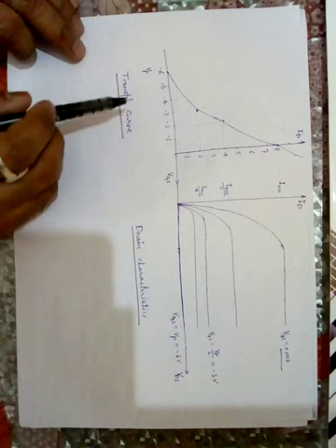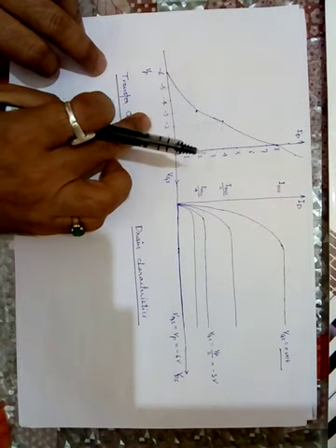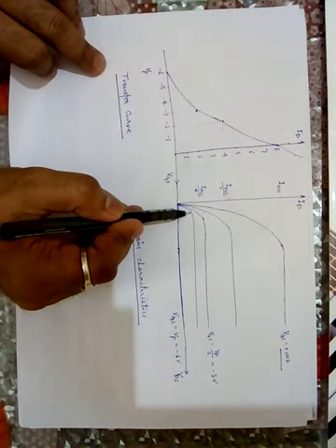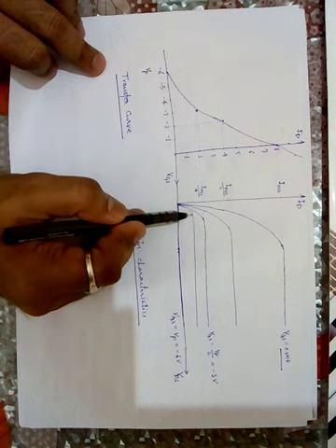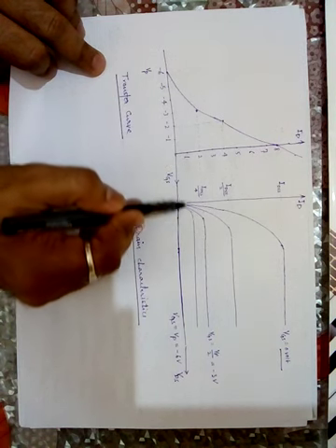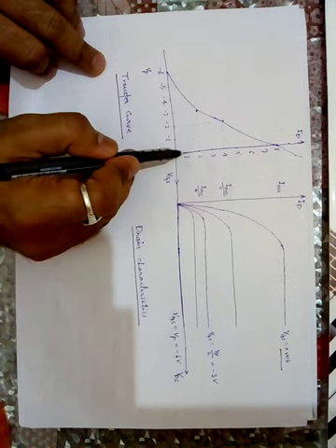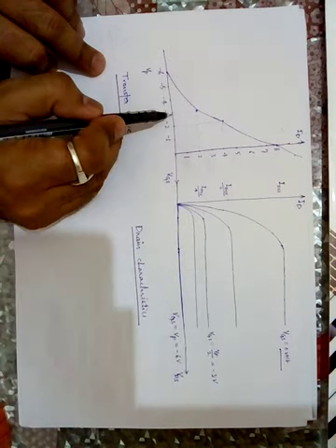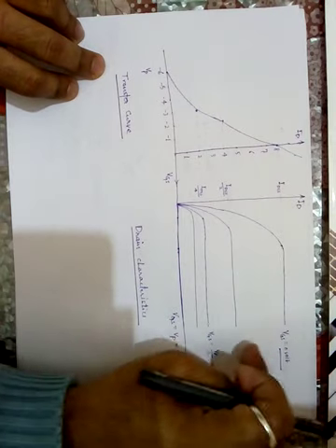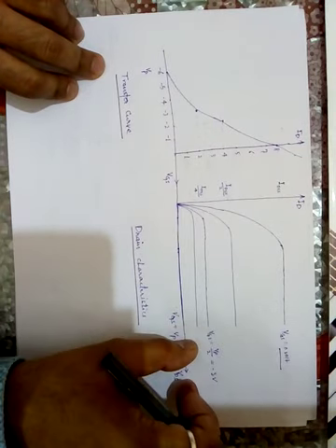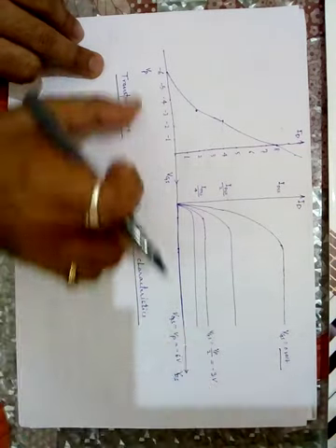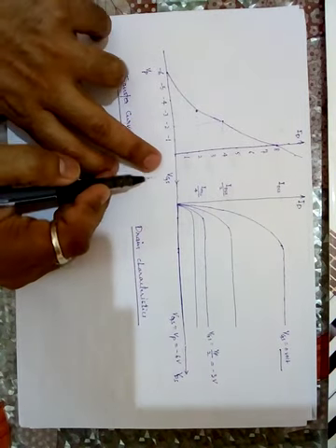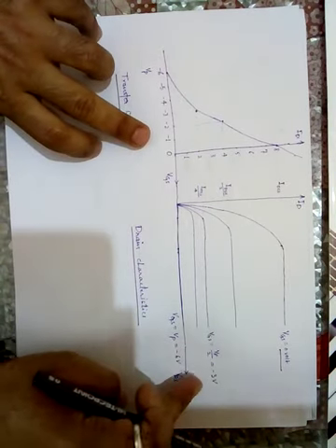So here we have drawn the transfer curve. If we connect this dotted line to the back side, then this is IDS at VGS equal to -3. Whatever VGS is written here, I have collected and written on the x-axis. See here, this is 0 and this is -3.